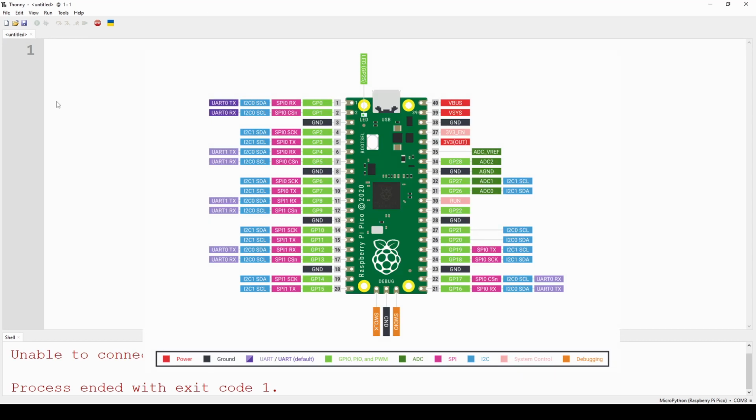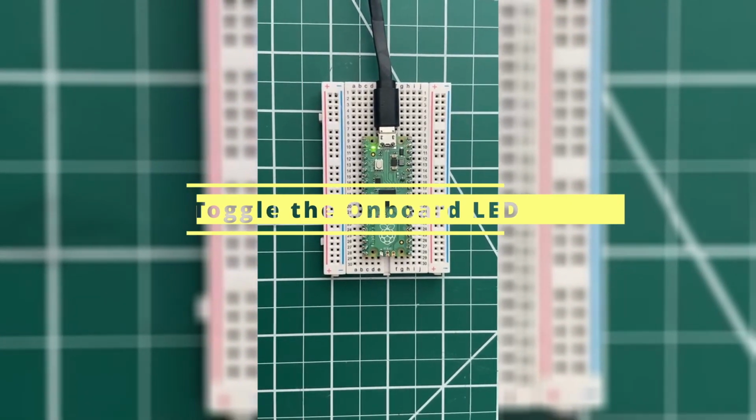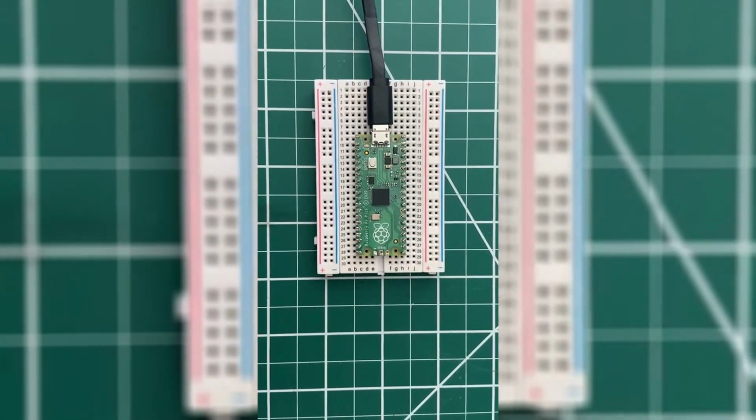On the screen is the pin layout for the Pico that will need to be referenced for whatever projects you plan on doing. In our first case, we will be referencing the onboard LED, pin number 25. The code to toggle the onboard LED is the simpler of the codes we will use today and will be a good base to build from.